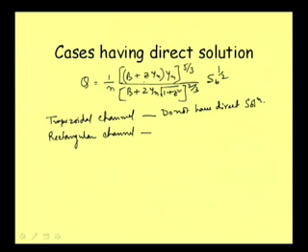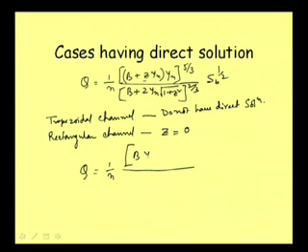See, when it is rectangular channel, it means that this z value, that is the side slope z, is equal to 0. And then for that, if we write this expression, you can see that Q is equal to 1 by n, then b into yn, simple, because we all know, and this will be 5 by 3, and the side slope part is also simple, that b plus twice yn to the power 2 by 3 and S to the power half.